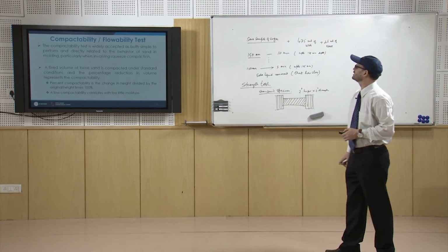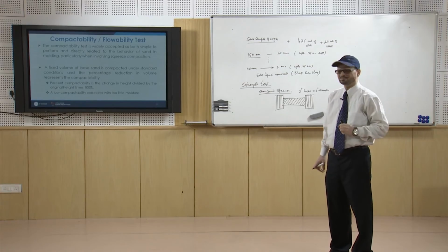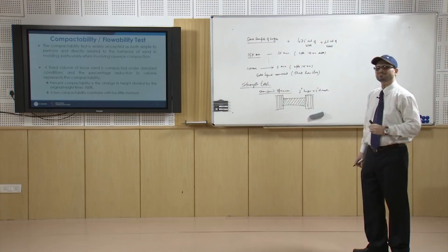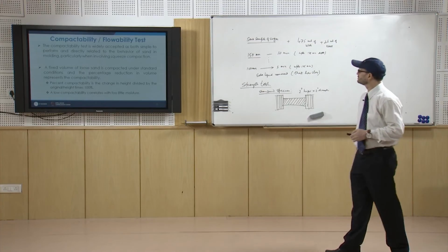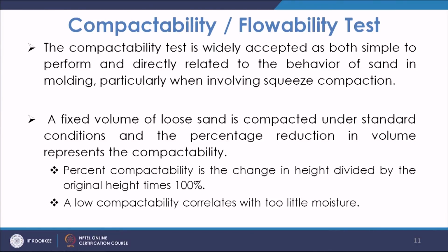Compactability or flowability test. So, how much can it be compacted? For this test, basically what we do is, a fixed volume of loose sand is compacted under standard conditions, and the percentage reduction in volume represents the compactability.